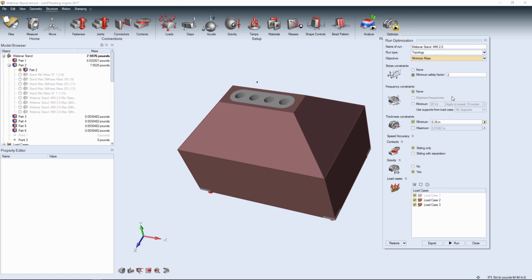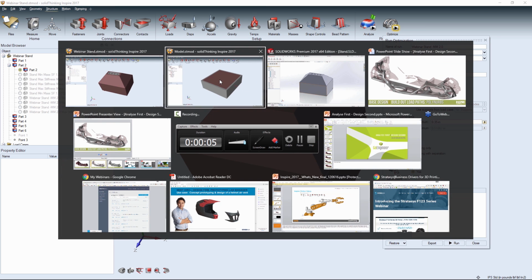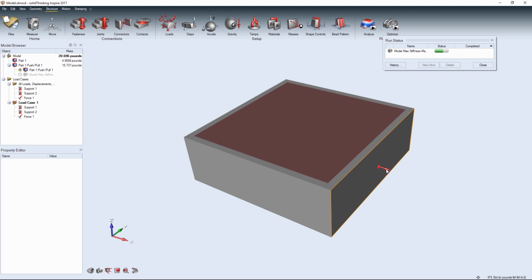Okay. And for this reason, because we are dealing with factors of safety, it's really important that our loads are accurate. When we're doing stiffness, our loads don't necessarily have to be accurate. They just have to be relative to each other. So, for example, in our last study, in this shape here, whether or not this load is 5 pounds or 5,000 pounds, the shape that gives the maximum stiffness at, say, 30% is going to be the same, because that's the load path.